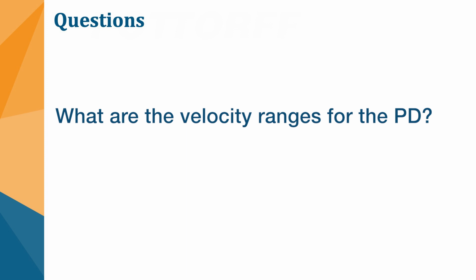When you get below 500 or 600 feet per minute, we do have to go to special construction for the airflow measuring equipment from Air Monitors, whether that's the Veltron 2500 and the probes associated with that. But typically, when you're getting that low, even with the thermal dispersion units, your accuracy is going to suffer quite a bit. And we can get you some. I know they're not on the submittal sheets right now. We can look into that.